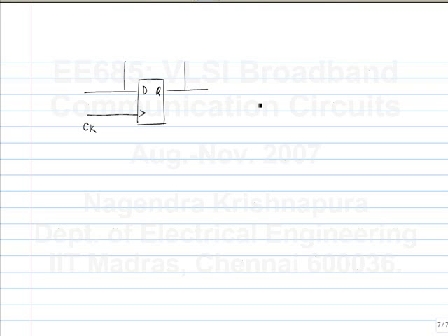If the clock has jitter. No. There are two separate things. What is jitter and what is duty cycle? No, I mean the data edges will also have jitter, right? That is true. I mean that is true with anything. So if the clock has jitter, the output of the flip-flop will have the same jitter, right? If it's an ideal flip-flop, when the clock transition occurs, the output transition occurs. So if the clock edge is jittery, the output edge also will be jittery.